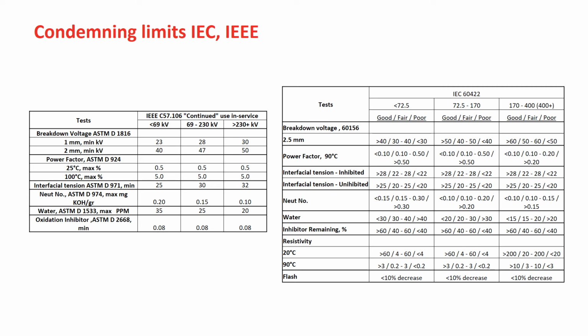Oxidation inhibitor test indicates the amount of antioxidant additive remaining inside the oil formula. The antioxidant additive is a consumable additive that will sacrifice itself to protect the oil against oxidation. So, an in-service oil will use up the oxidation inhibitor additive during the operation.